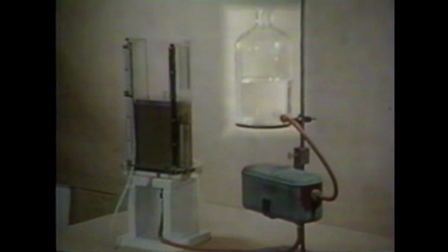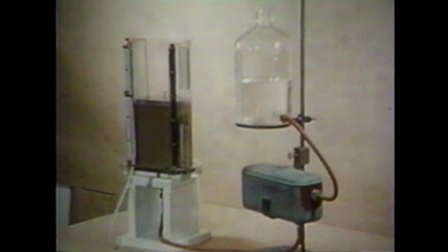Researchers placed a soil sample in a clear plastic cylinder above a porous stone through which water was supplied. The soil is a type of New Hampshire silt known to be frost susceptible. A lead weight representing 6 inches of pavement was placed on top of the soil. 2 scales measured the amount of movement, or heave. One scale was attached to a cylinder, while the other was allowed to move freely with the weight on top.